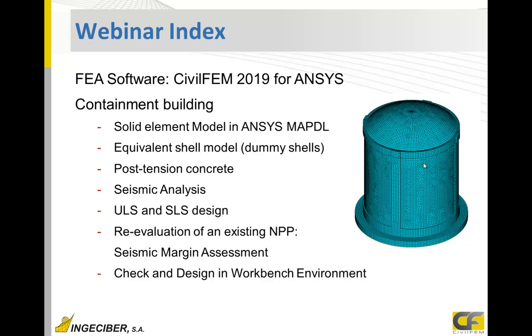This equivalent cell model integrates those stresses, and after integrating stresses on the solid element model, we obtain forces and moments. Codes and standards are based on forces and moments to calculate reinforcement amount, cracking, and all data. So we will have the option of performing checking and design on a solid element model.